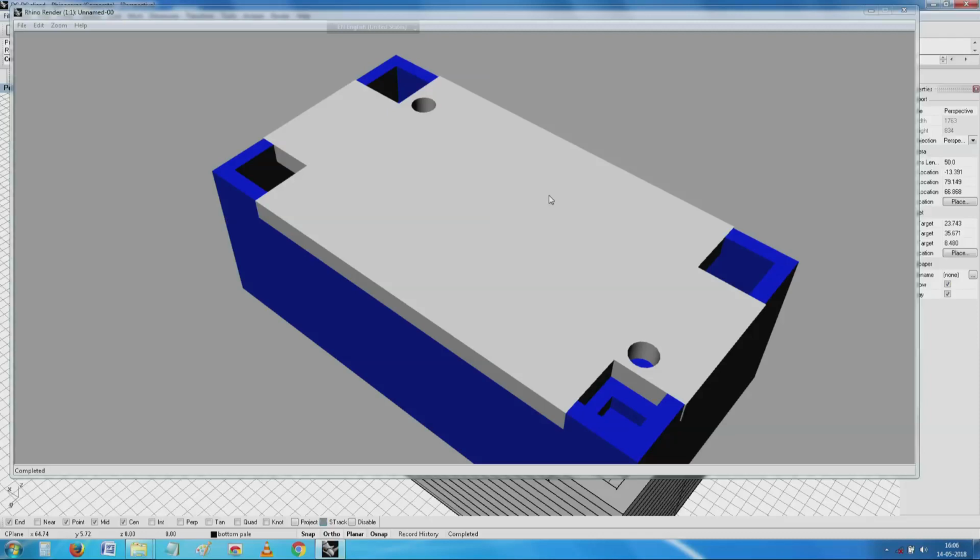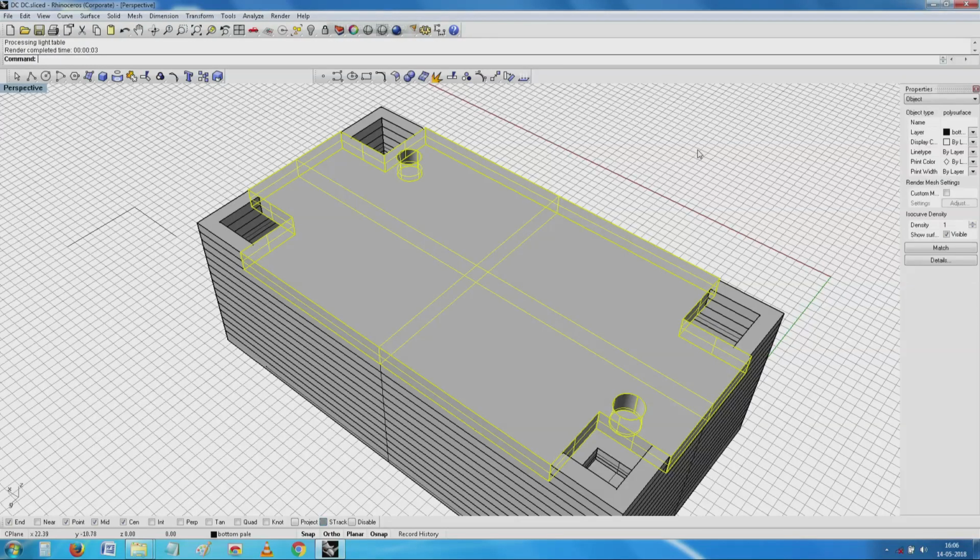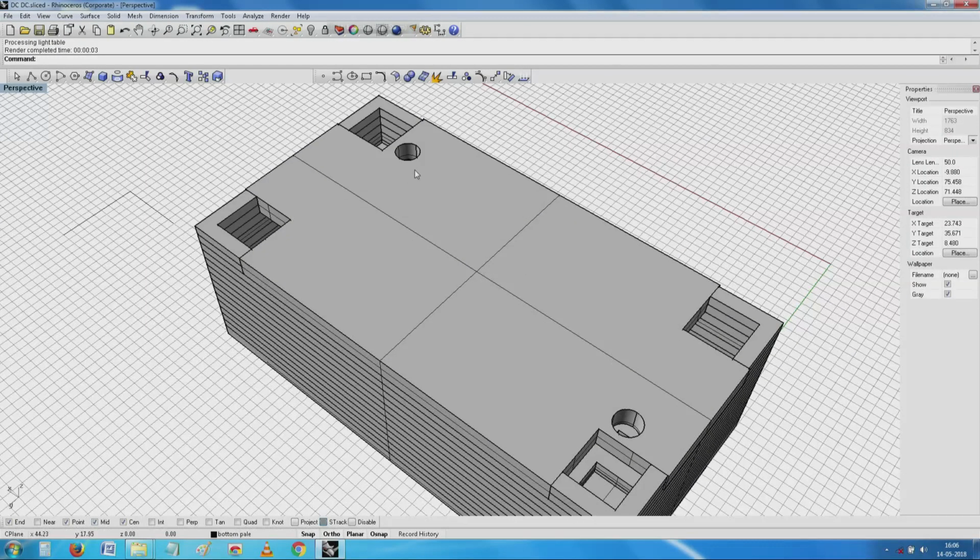Then I also make a counter sink or a counter bore, so that everything is flush, and in fact this is where a little bit of improvement can be done, saying once you have a heat sink and once you have a printed circuit board and all that, why do you need these 4 corners at all for anything? Why can't the unit be built directly onto the heat sink? You understand, no? And a cover can be placed over it.